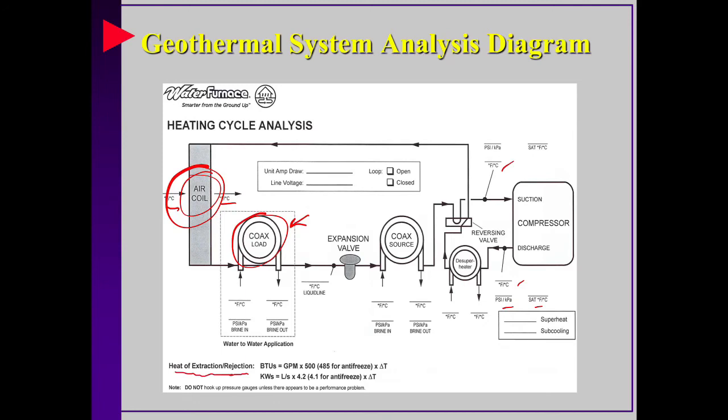From a diagnostic standpoint, they place a lot of emphasis on temps and pressures. So your temps going in and out, and your pressures going in and out. And these would be, of course, on the water side or the fluid side for the source. So those are all, and then obviously water applications that said, in and out pressures, in and out temps. And they need to know those things.